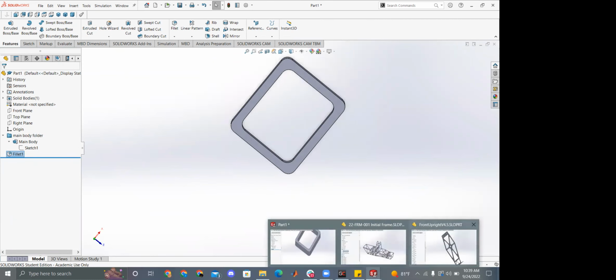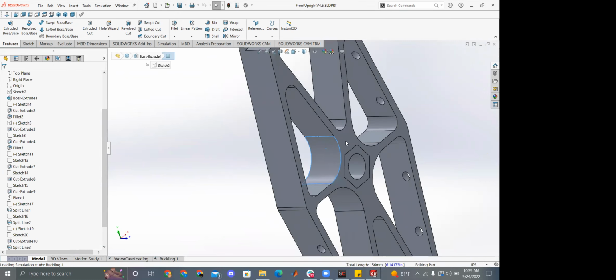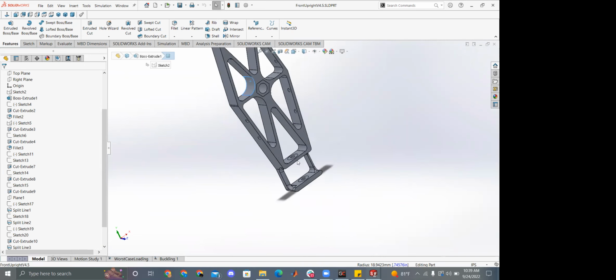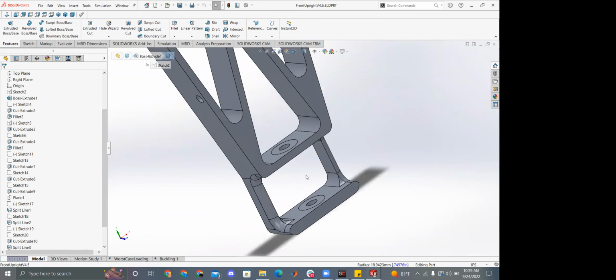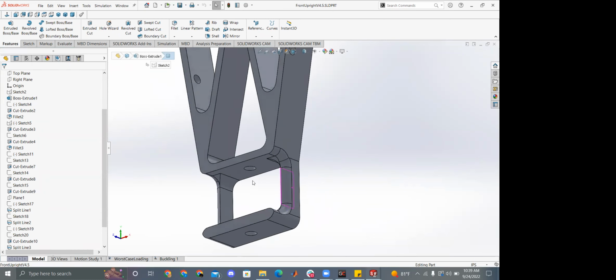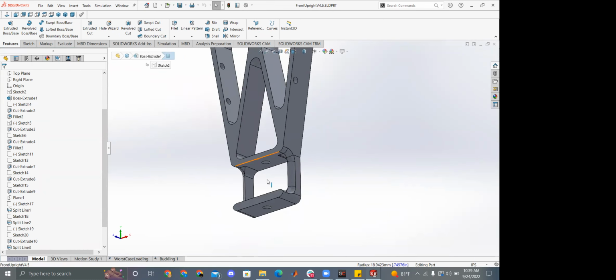Most of our parts, you'll see with this one especially, need fillets because they're taking a lot of load. It's mechanical, right? In a car, we're going to be preparing the car to hit bumps. So we want areas that are going to be loaded a lot to have pretty exhaustive fillets.